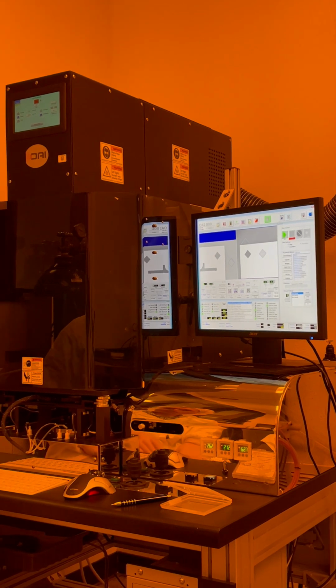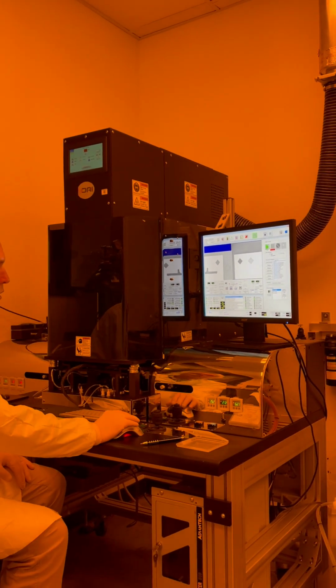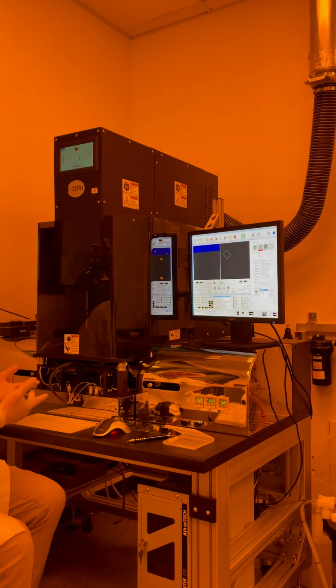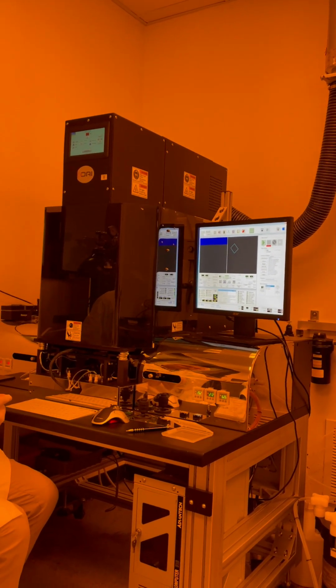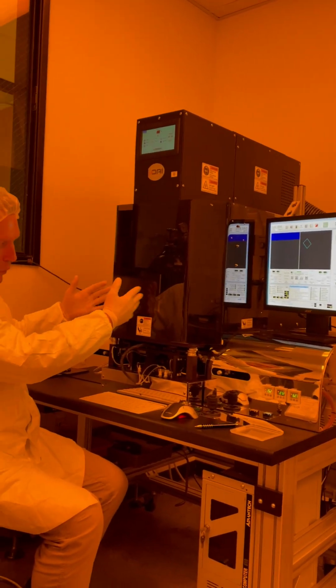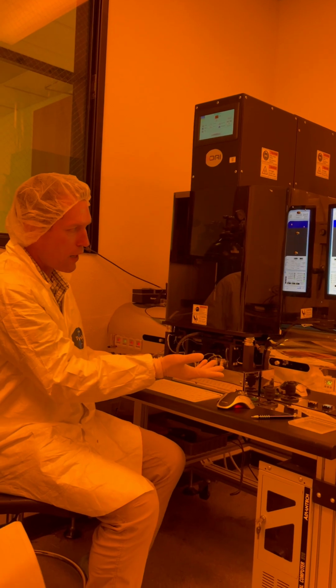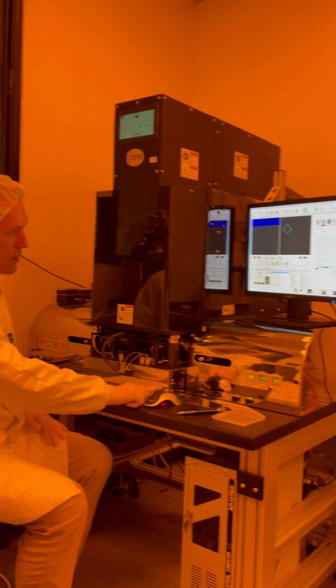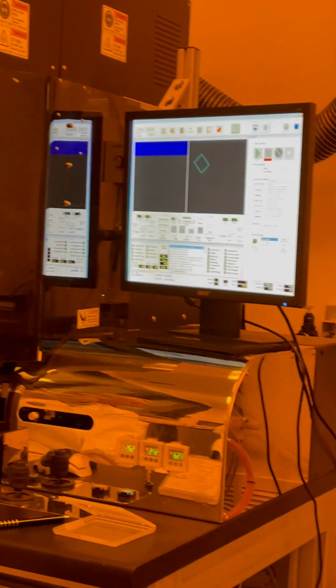Oh, I didn't show you one other thing. After you initialize the system, the optics are going to be back out of the way, and you load your process file. Then to bring the optics in to make sure you can see your microscope, you press this button, and this will bring it to wherever you have saved that optics position.